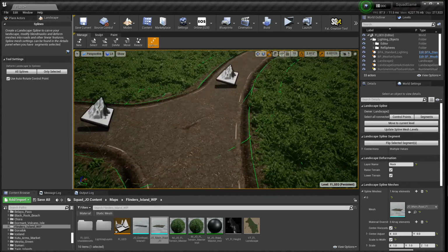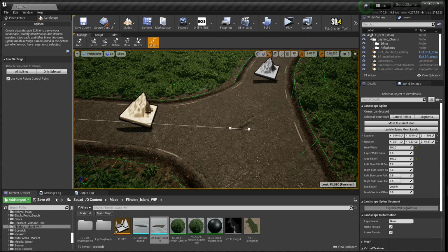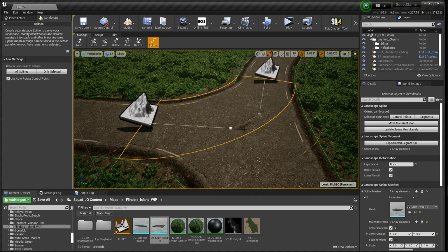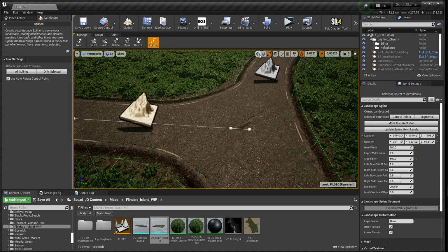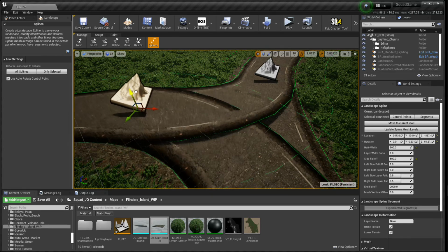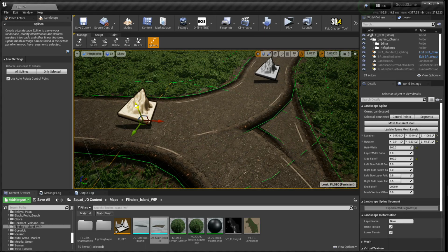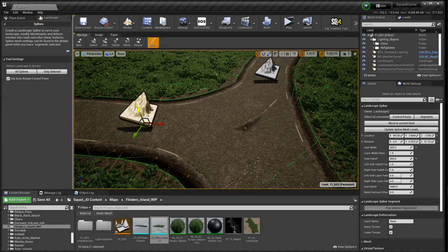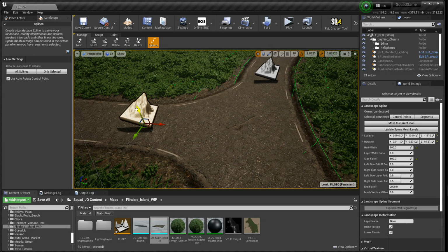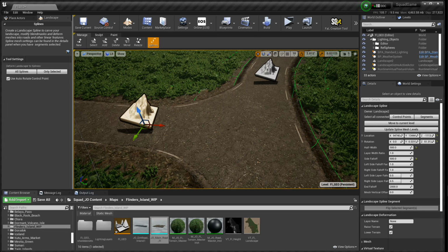In here we've got a little bit of this crossover, which is a bit of the mesh. This mesh here is bleeding through the other meshes. So the way to fix that is you can play with the heights of these. See how that's, okay, so if I raise it right up, you can see how they're all crossed over and it gets messy, right? Just take it down gradually until you can hide it, or mostly hide it. Like, that's pretty good. Yeah, in fact, I'd stay there.